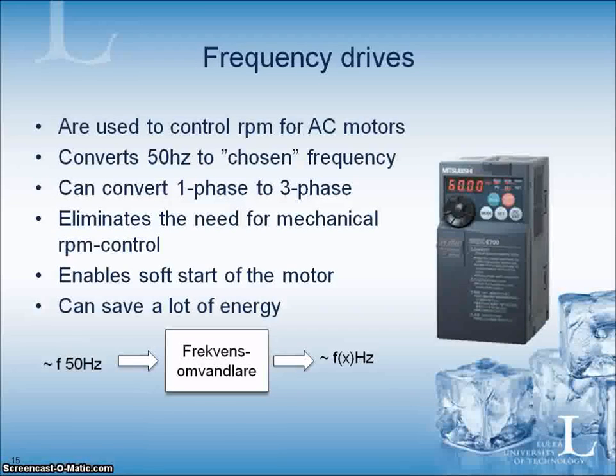Frequency drives are something you need to control the AC motors and also the brushless DC motor. They are used to control the RPM for AC motors. Normally it converts 50 Hz to the frequency of your choice.